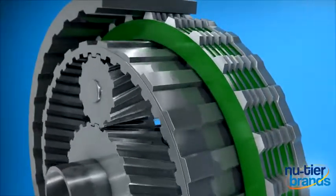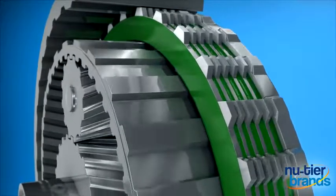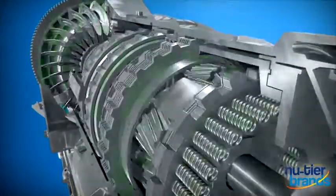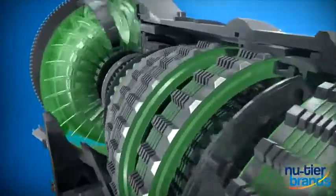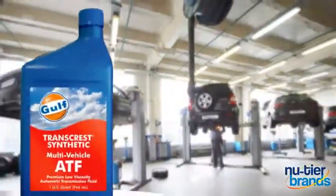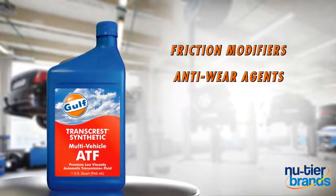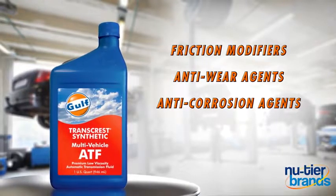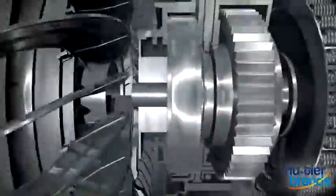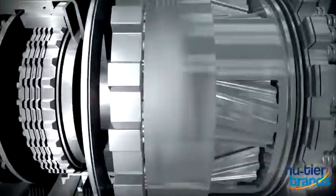The ATF precisely controls friction in the clutch packs and maintains it throughout the drain interval, perhaps the most important property of an ATF. And finally, it provides lubrication to the hundreds of moving parts, even under high temperatures and extreme pressures. Modern ATFs include friction modifiers, special agents for anti-wear and anti-corrosion, and chemicals to enhance high heat performance and maintain a specific viscosity. So using the right ATF is critical to the performance and long life of your transmission.